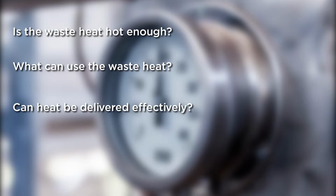Can the primary process deliver energy to the secondary process in time? Distance will be a limitation when heat loss is considered. As distance between the first and secondary processes increases, the transfer efficiency decreases. If the distance is too great, heat recovery is not economical.